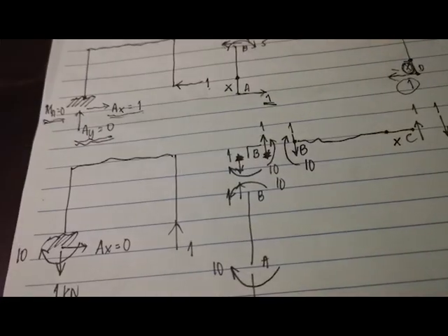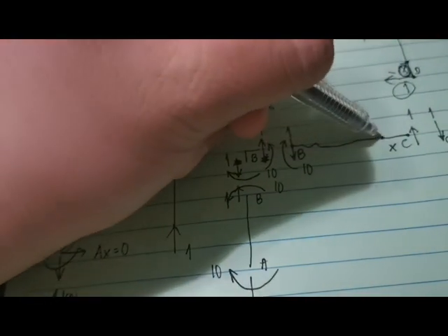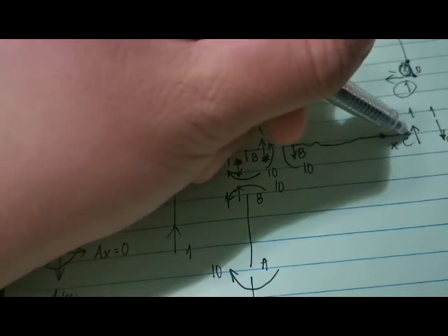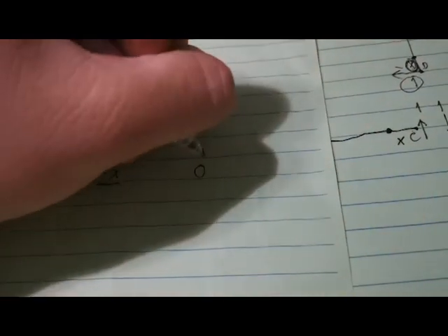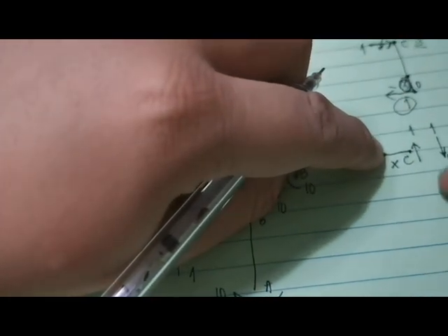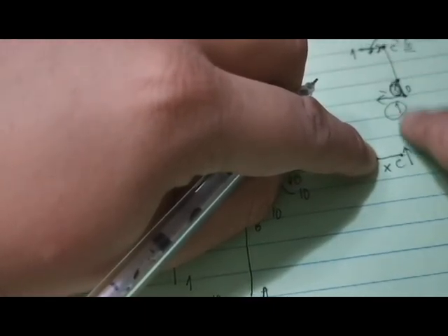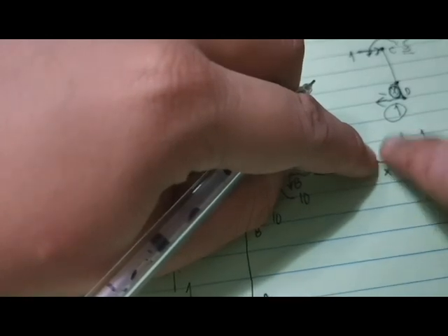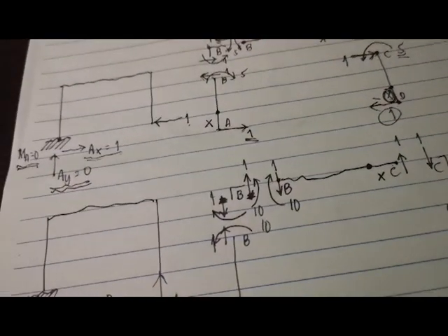again going back, we don't have a moment equation here, so therefore from the table this will become 0. Okay, then at member BC, if we measure your moment from point C going to B, our moment equation is equal to X, but as per the direction, we know that the 1 kilonewton is causing the beam to smile, pinapangiti niya yung beam natin, so this is positive.